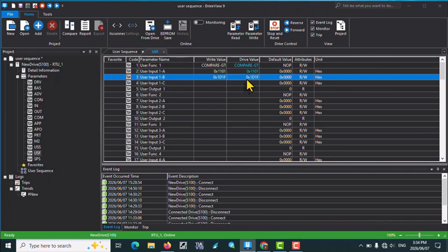All right. I said that if my A is greater than B, it will transfer C to the output. Okay, so in these inverters, the address for start and stop is address 6 hex. If the value at this address is 1, this inverter will stop. If it's 2, this inverter will start in the forward direction, and if it's 4, this inverter will start in the reverse direction. Now, for example, in this video, we want it to start in the forward direction. That's why we need to set address 6 to the value 2.